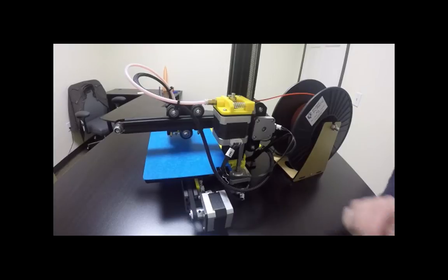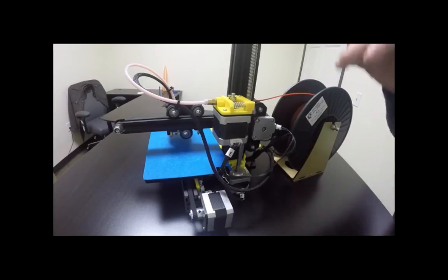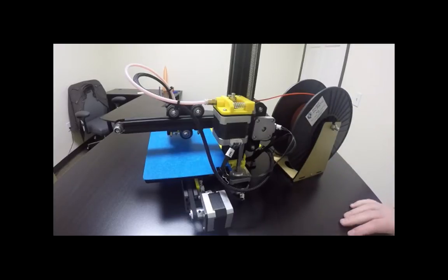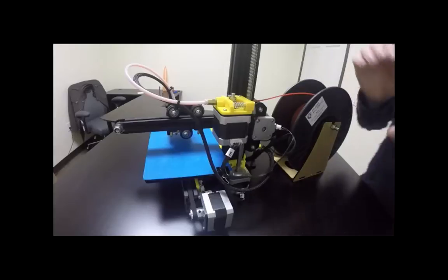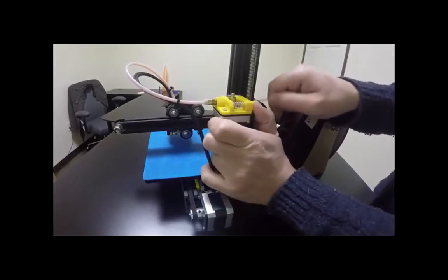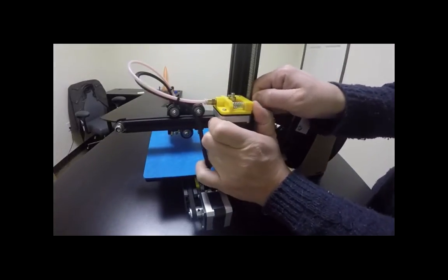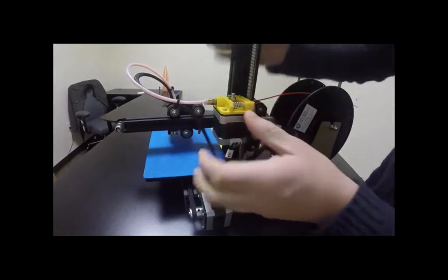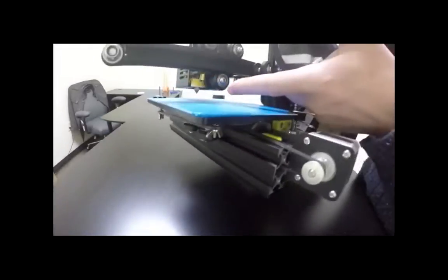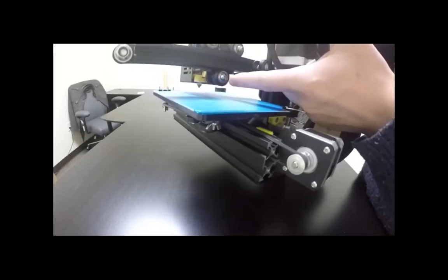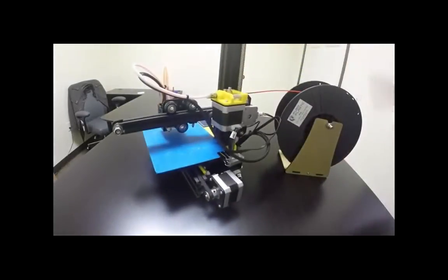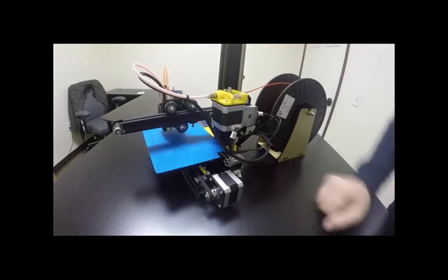And then when you load the filament, you'll want it to go all the way up to the maximum temperature. So what temperature is that now? It's at 163 out of 190. Okay, awesome. So when it gets up to 190, you're just going to squeeze this and then push this again to push some more of the filament through. And then you'll see some of it coming out of the end right here, out of the nozzle. And when you see some coming out of the nozzle, that's how you'll know that it's pushing out the old filament.